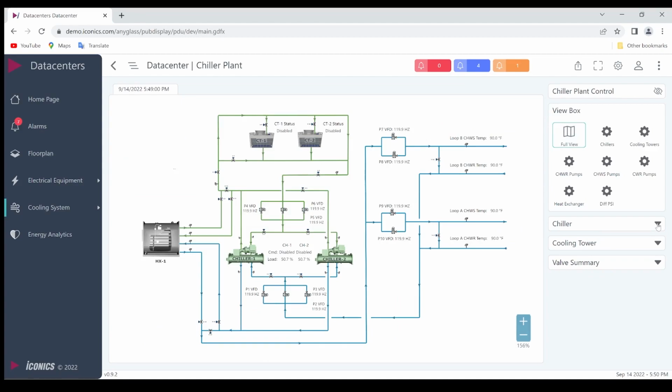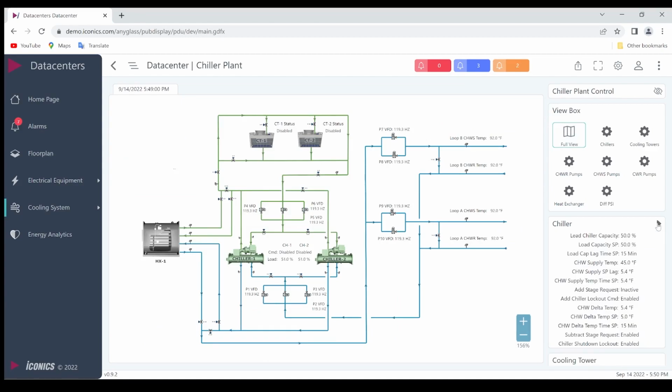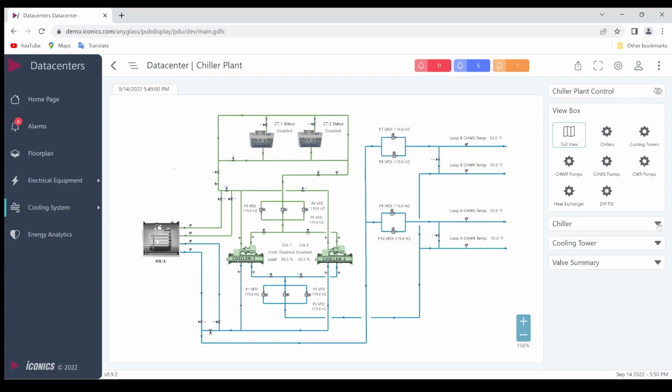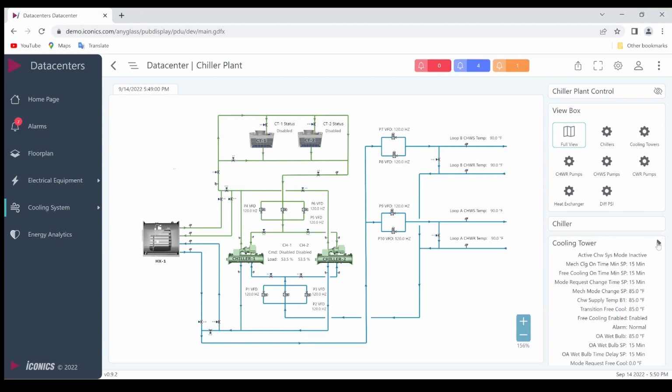Now, also, I can pull in, as more and more, a chiller plant has usually quite complex control. It has tuning parameters to set up its sequencing. In this case, I'm going to all the tuning parameters, and I can sit there and modify these parameters if my security rights allow me to do so. I have various control cooling times set parameters that I can pull in for the cooling towers itself.